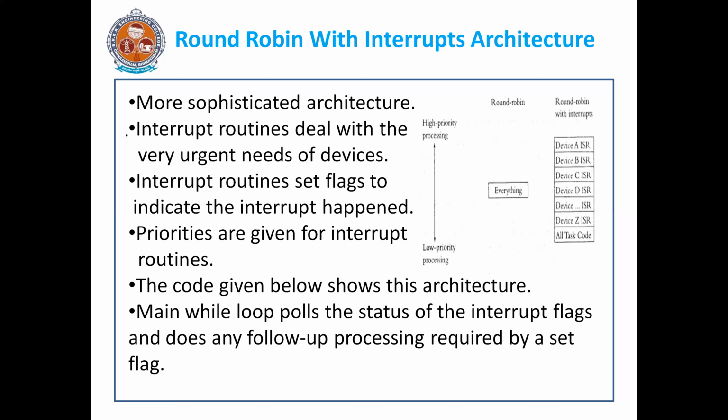Interrupt routines deal with the very urgent needs of devices or hardware. The interrupt routines set flags to indicate that the interrupt happened. Priorities are also given to the interrupt routines. So in addition to the round robin architecture, interrupts have been added to the architecture.